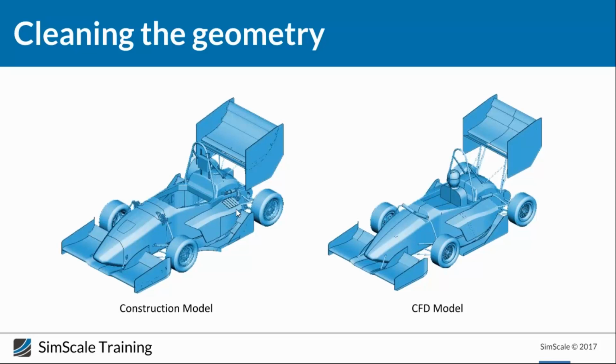Tushar wants to know something about vortex generators. His question is that they are quite small, and whether this means they should also be defeatured. Basically, vortex generators are small, at the same level as the boundary layer. I don't suggest to defeature the vortex generator, but what I suggest is to create a really high quality mesh over the vortex generators, so you get the right shape of it and can predict what it will do to the boundary layer.